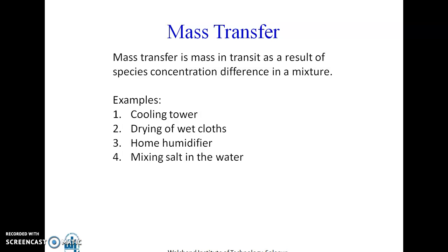When it falls through the perforated trays, it vaporizes because of the temperature difference and unsaturated air. So the cooling tower cools the hot water by releasing the latent heat in terms of vapor. Those vapors get diffused in the surrounding air. This is nothing but heat and mass transfer. Heat transfer in the sense of cooling of water, and mass transfer in the sense of the evaporated vapor getting diffused in the surrounding air.